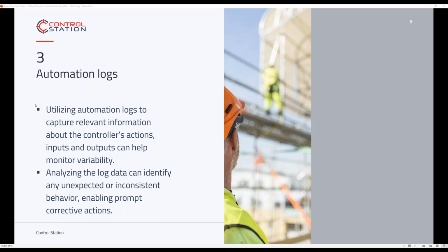And this can also be down to the layer of using some of the diagnostic information that is in smart instrumentation, right? We've invested a lot of money on smart instruments, and so those create events and logs for us to be able to investigate the performance of individual valves or individual sensors and so forth to make sure the calibration is correct, that the signal coming in is appropriate, that it doesn't need to be adjusted in any way, and that the signal is correct.